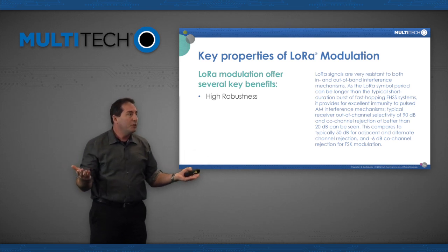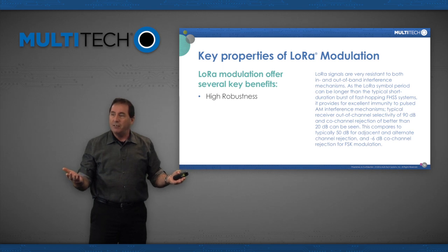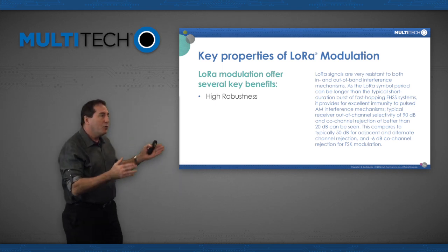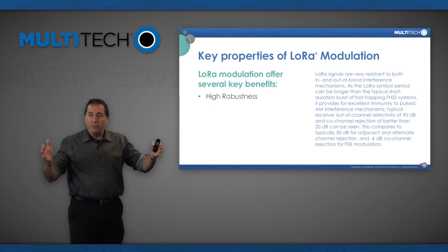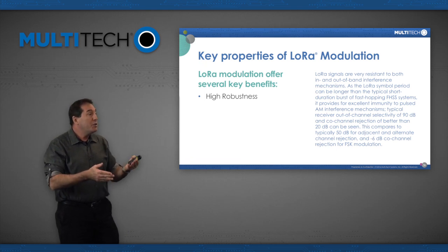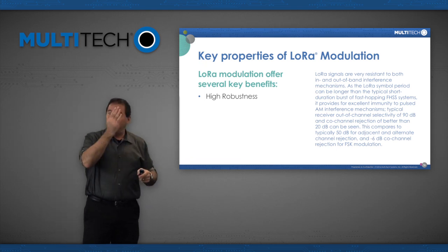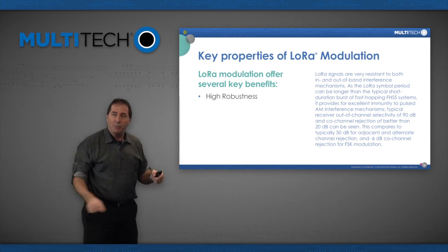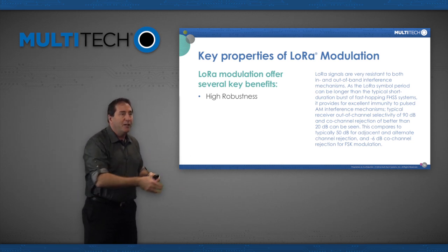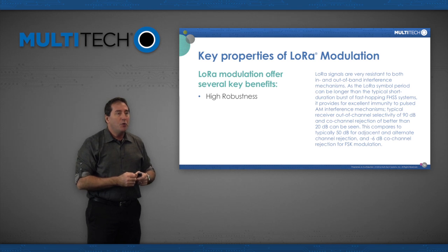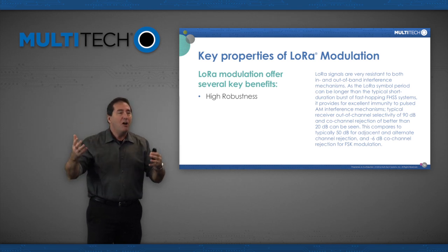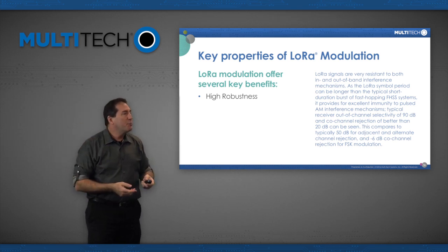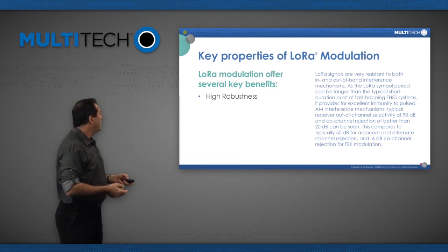Did anybody have difficulty understanding what I was saying? No. And that's why LoRa, being a digital spread spectrum system, when you get other interferers, which are generally those narrowband FSK radios, it's like pounding on a table. Each one of those packets going by is like one hit on the table. And so we can talk all day long and not really be affected too much by interference.